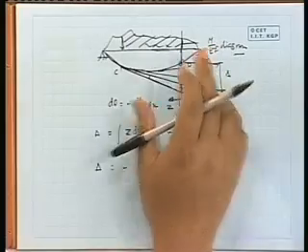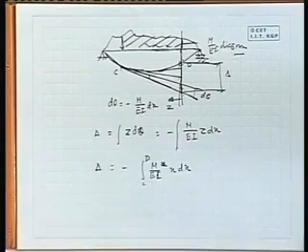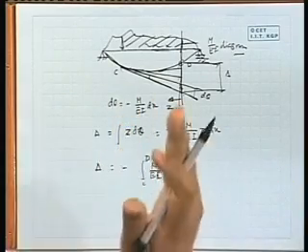First was related to slope calculation. The beam will be given, loading will be given, reactions we can calculate, we can draw the bending moment diagram. That bending moment diagram can be divided by EI. If EI is constant throughout, it will be uniform scaling. It may be a beam having a different type of EI. So, it will be just divided by EI at the corresponding range.